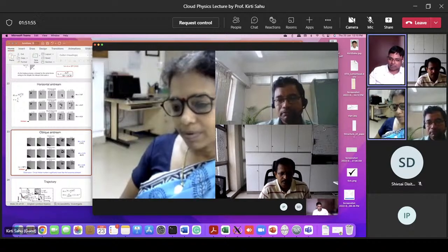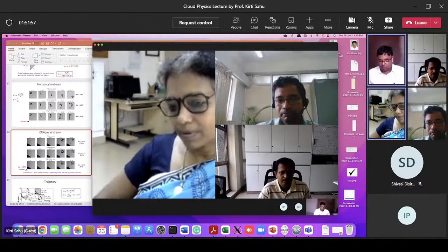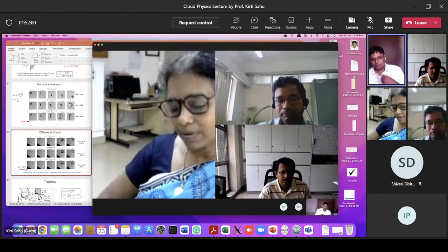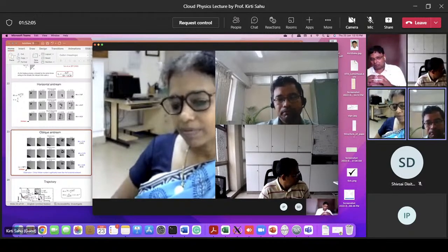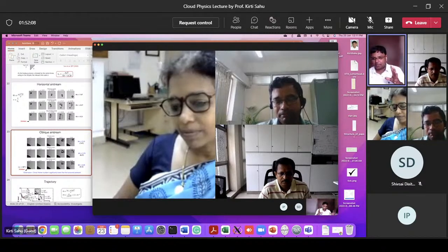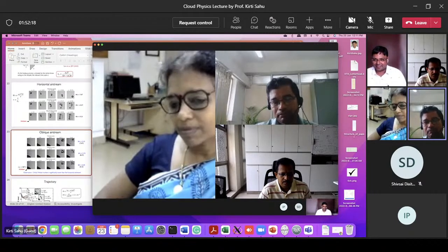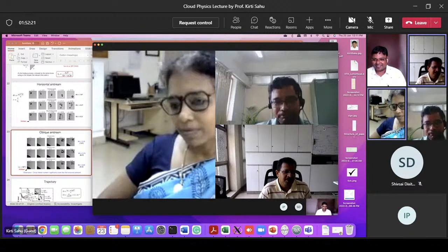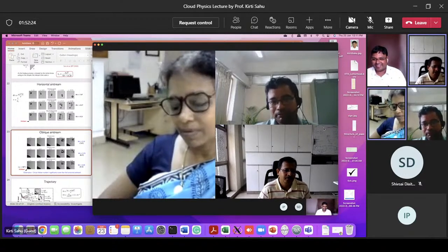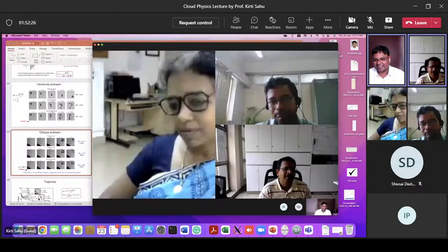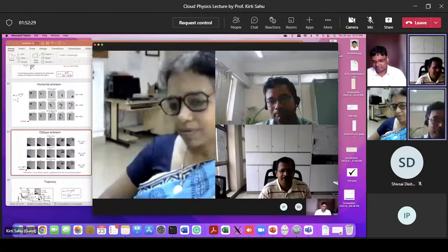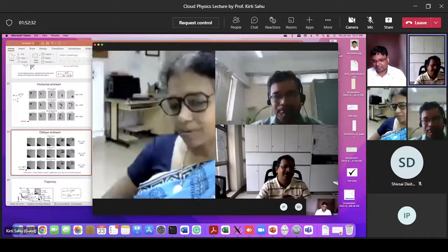If the size of the drops is very small, the curvature is more, and in those cases surface tension will win, and hence the droplet will be spherical. But once it becomes slightly bigger, the inertia and the surface tension become comparable, and they will form non-spherical shapes. It can even keep changing shapes, spherical to non-spherical. So what he explained, the surface tension and the gravity, it's a dynamics, they can keep